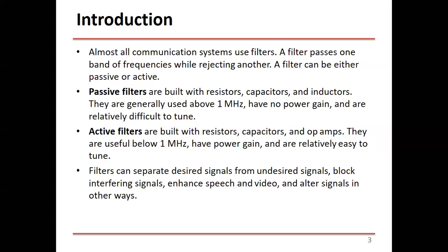Of course, with the development of technology, we might see some active components that work in higher frequency. But in general, if you'd like to design filters in the high frequency above 1 megahertz, you usually use passive components only.